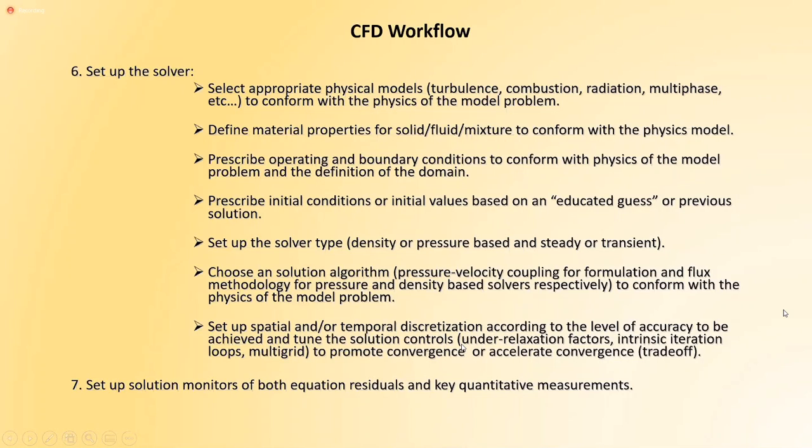The under-relaxation factors mean I take a step, but then take a step back, a little step, because I think a big step is going to make me diverge.